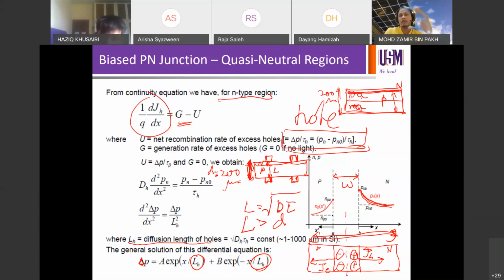So that's like 1/1000, right? 3 order of magnitude thinner than the original thickness of the wafer. So we don't dope halfway through the wafer, because that's just too deep. So the typical thickness of the junction is like 200 nanometer of N-type on the whole P-type wafer, or 200 nanometer more or less of P-type on the whole 200 micron of N-type.